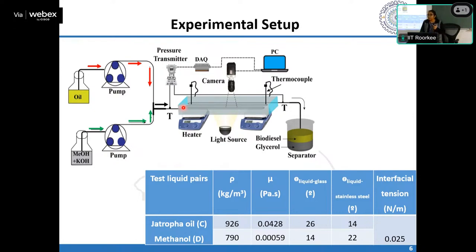That is very true. You have lowered the scale, so the diffusional resistance has gone, but you have laminar flow. So the transport process is now governed by diffusion, molecular diffusion itself. It's a low Reynolds number process, so the mass transfer is governed by molecular transport. So there is scope for improvement of the transfer rate in such reactors. And how you can improve the transfer rate further, there lies your innovation.